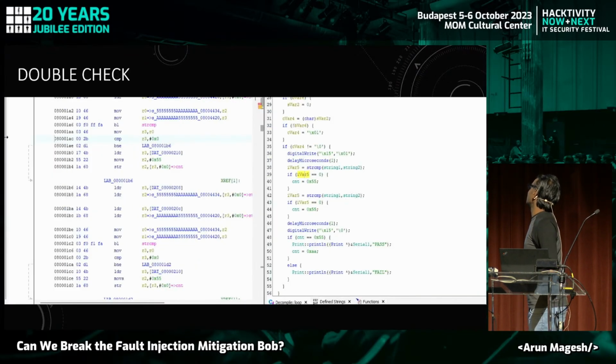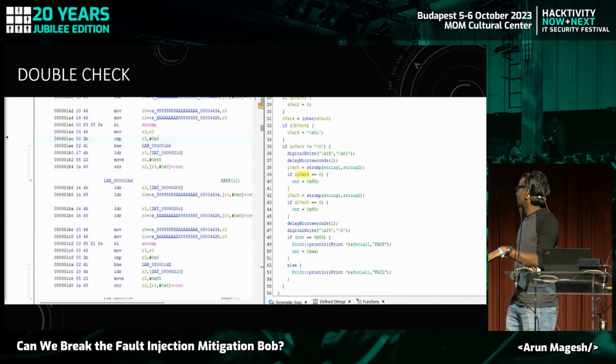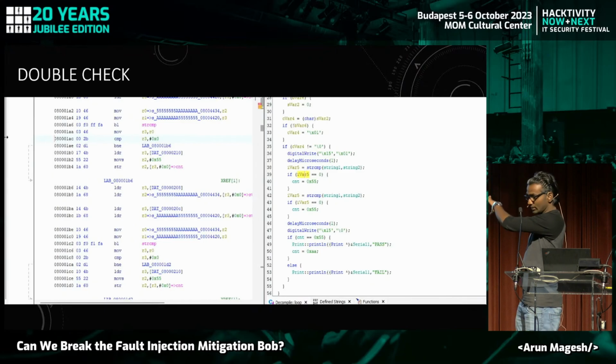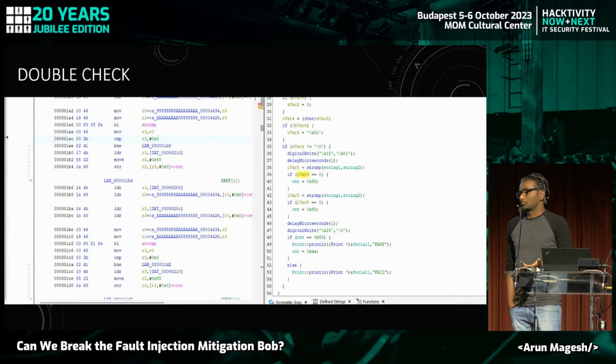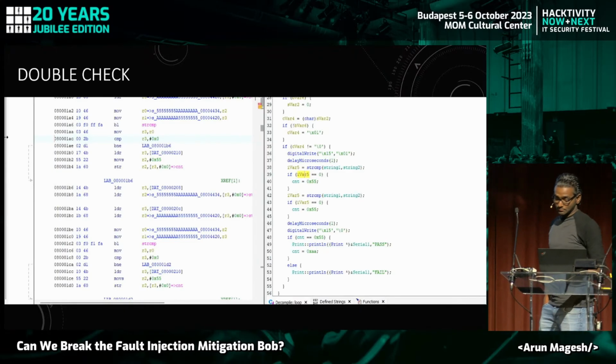Yeah, this is another one which people use. From a programmatic perspective, it sounds stupid. For example, you can do double checks, so you have the same string compare twice. You might ask, why not use an if-else condition? The reason is that if-else includes a lot of branch instructions, which means it just takes one glitch to break out of the branch and then go to your, let's say, pass test case in this case.